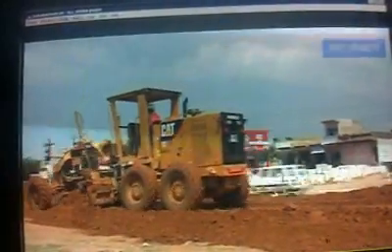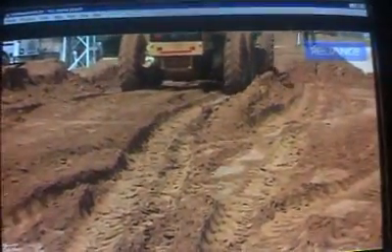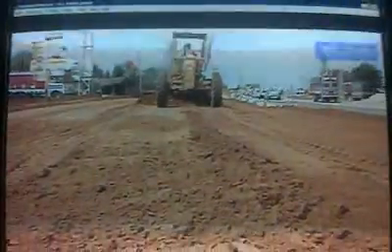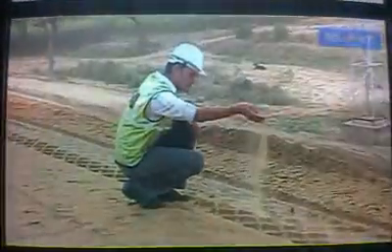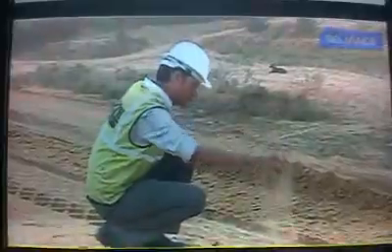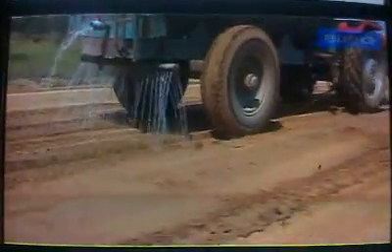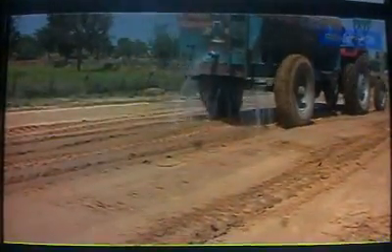Moisture content of the material is checked at the site prior to commencement of compaction, and if found to be within the desired limits, the same is made good. Wherever water is required to be added in such construction, water is sprinkled from a water tanker fitted with sprinklers capable of applying water uniformly with a controllable rate of flow to the surface but without any flooding.